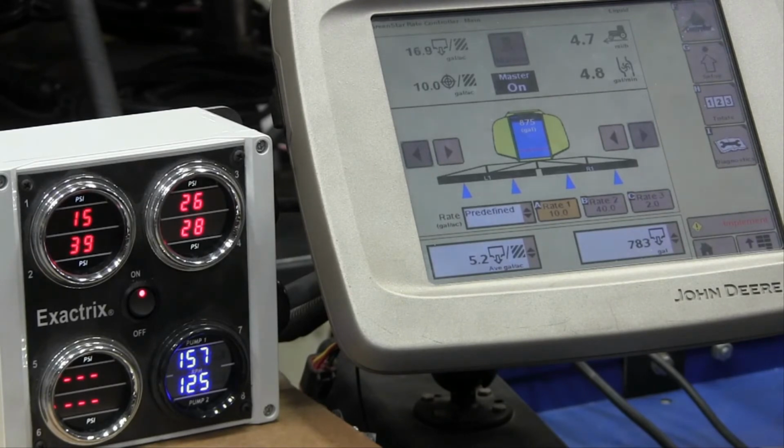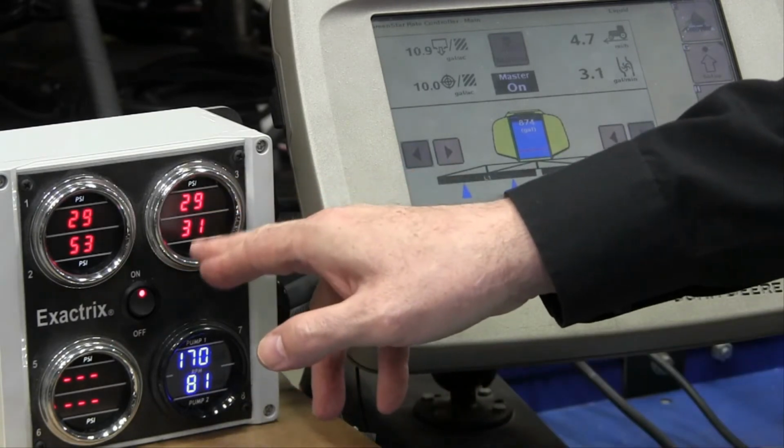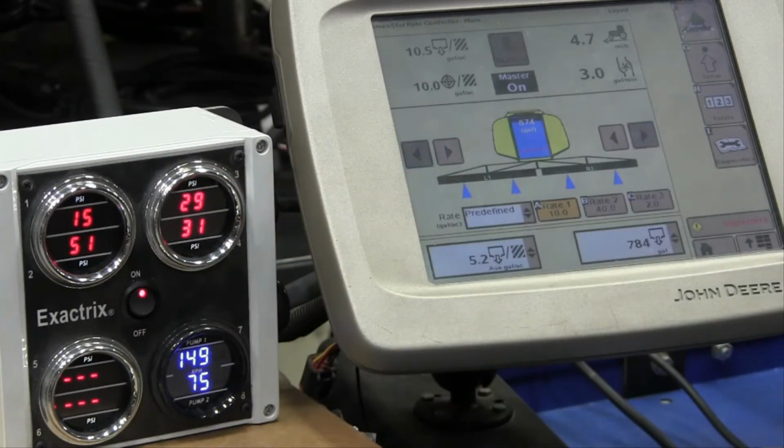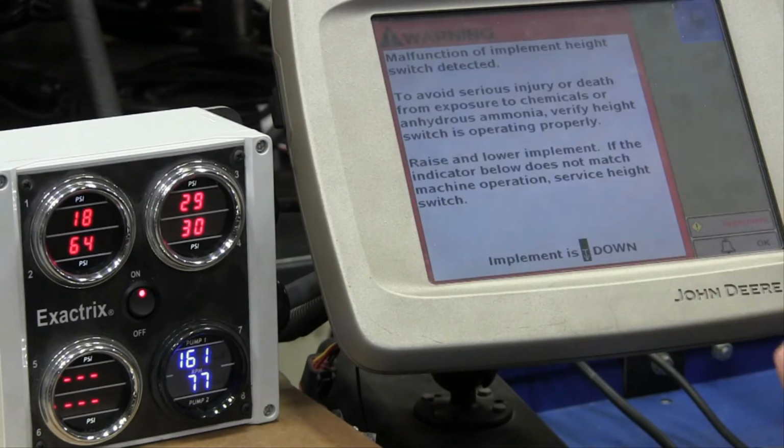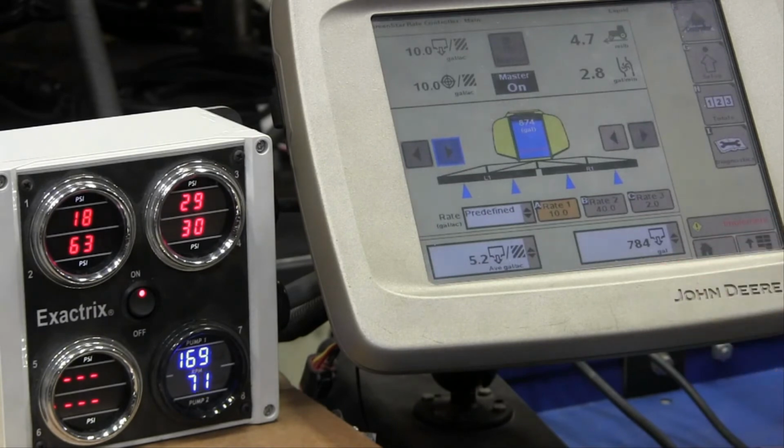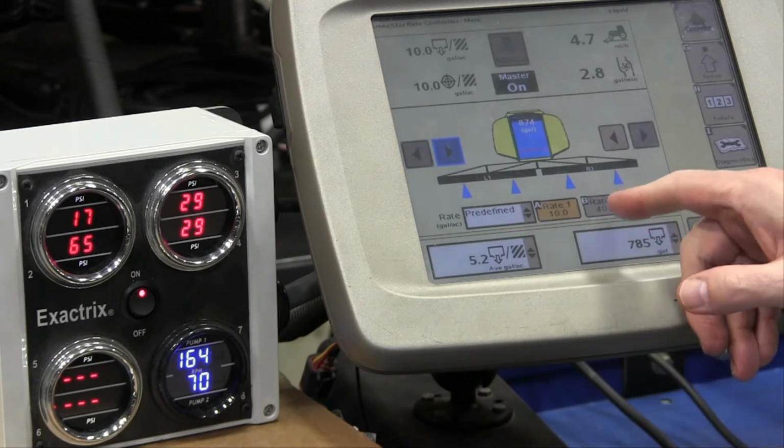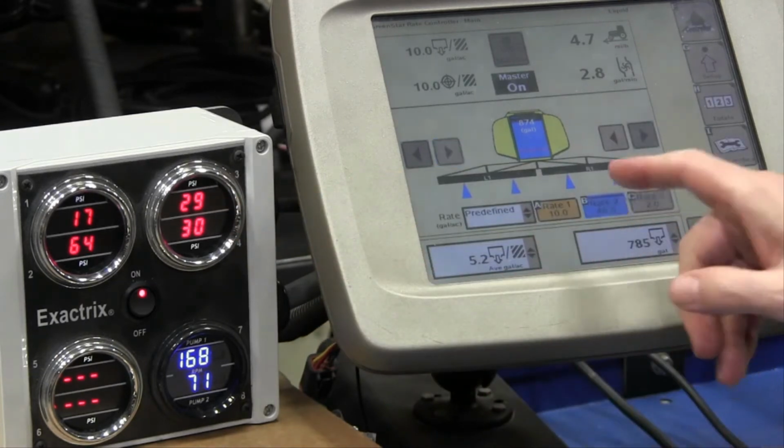Based on pressure, we're there. 7.5 seconds. Pump RPM's not quite down yet, but study that pressure and watch the pressure. Okay, we're going to go back up to 40 gallon. And so watch the pressure, see how quick it comes up.